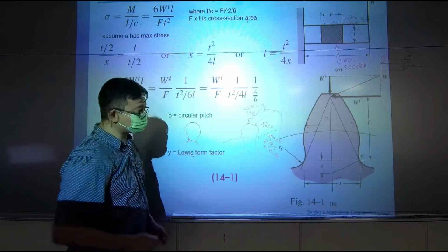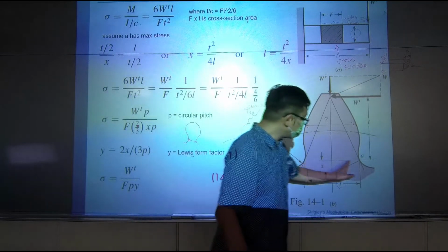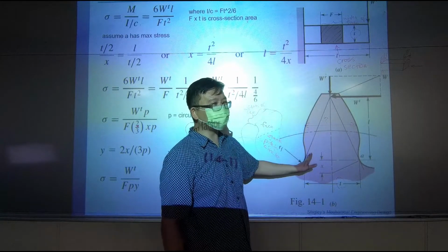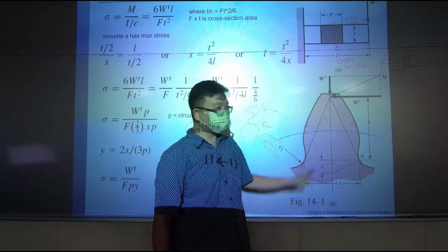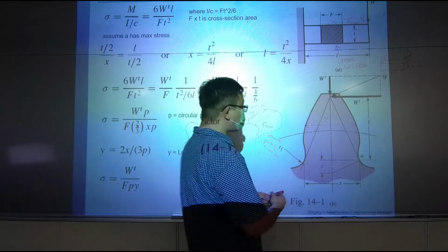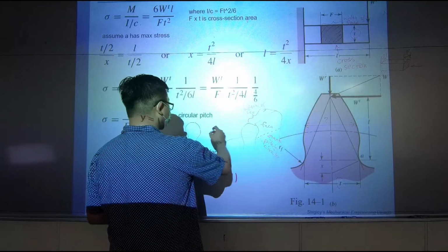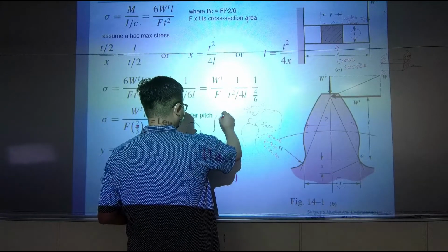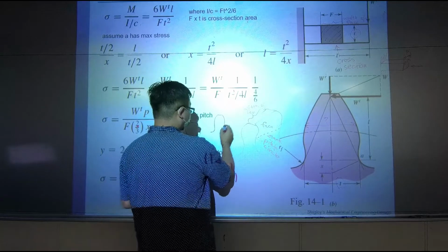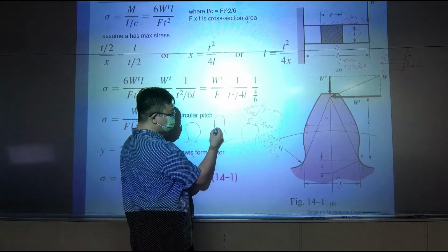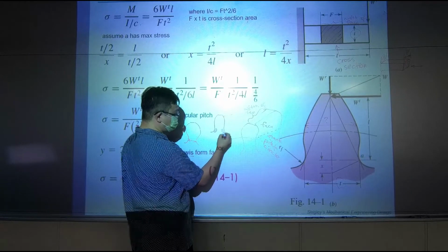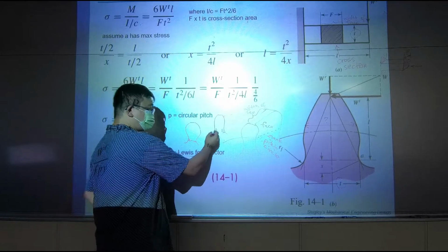And also, this width is more important, more related to the strength of the tooth. If I have a geometry like this, when I apply force, all the stress concentrates at the neck, right?